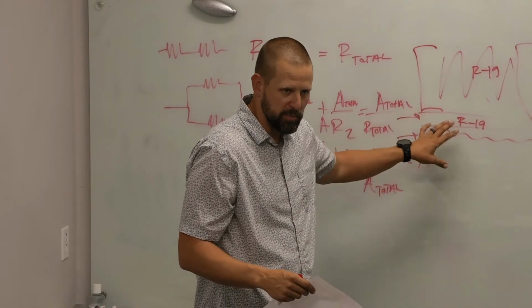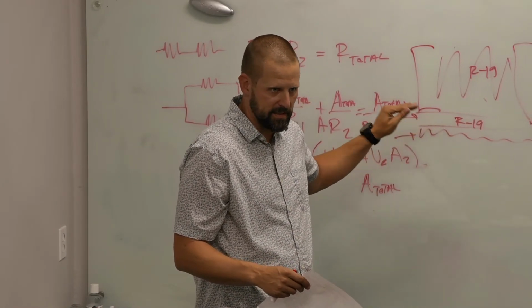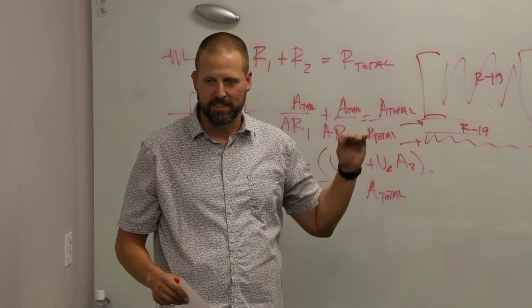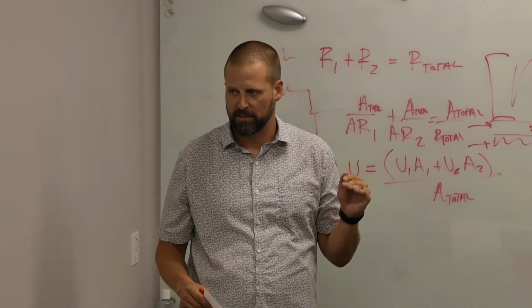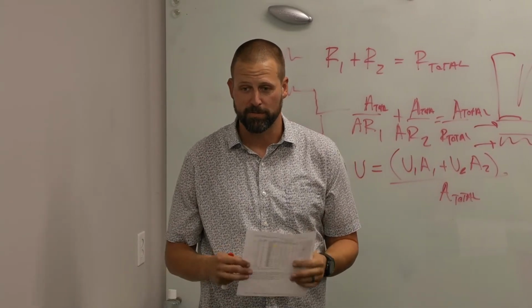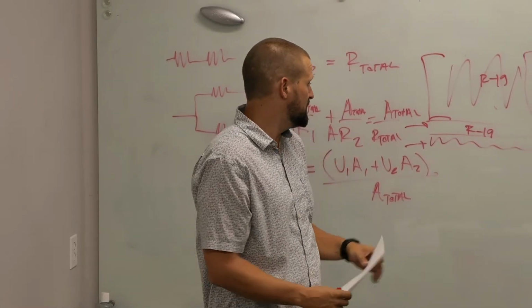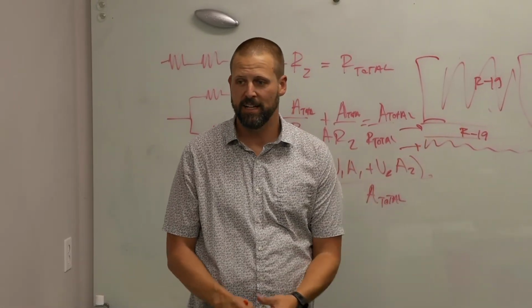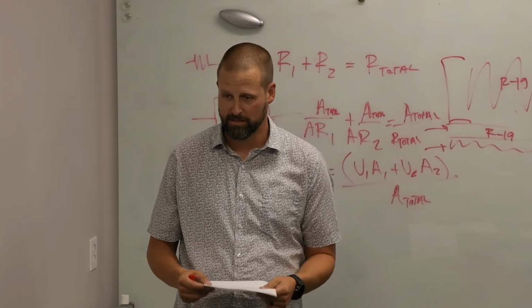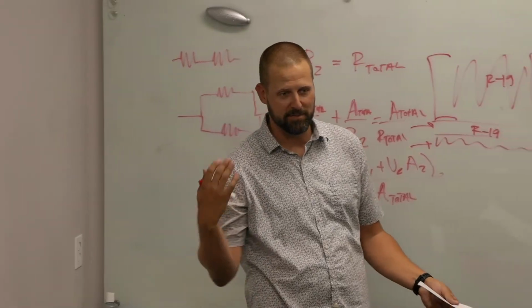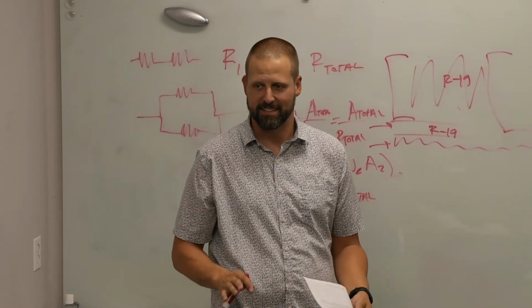how important thermal break is for performance, and I bring this up because this comes up in the field and is confused. We put together Title 24 forms, we put together load calcs and show on our plans, hey, you need R19 continuous insulation, and the general contractor will go out and be like, great, we need R19 insulation, they'll buy R19 batt, put it in the studs, and that's not the same thing.